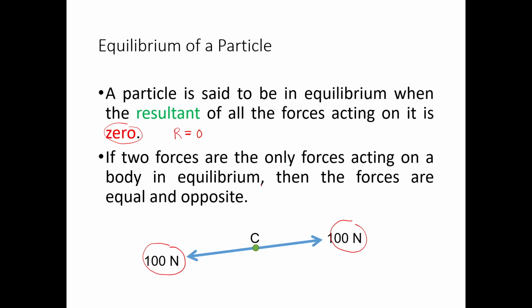Para equilibrium siya, di ba? Of course, in actual practice, we're not trying to achieve equilibrium, because if you reach equilibrium in our design, it is in the condition of impending failure. It's about to fail na, diba? Because it's in equilibrium. Since we are practicing safe engineering or safe architecture, we only allow forces lesser than the required amount of force that the building can handle. Later on, once you reach reinforced concrete design, you will still go back to this particular topic on equilibrium of forces.